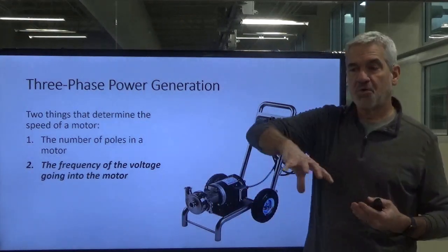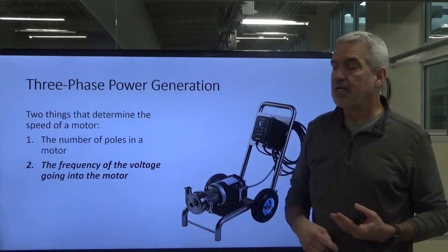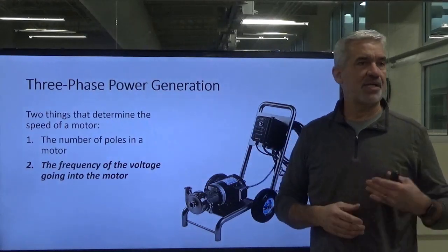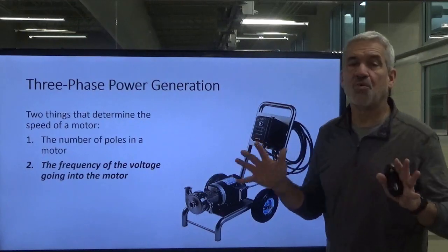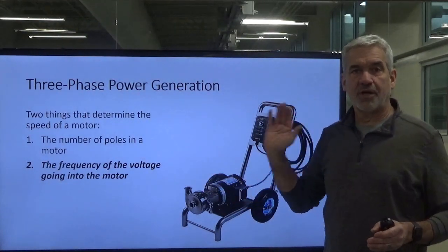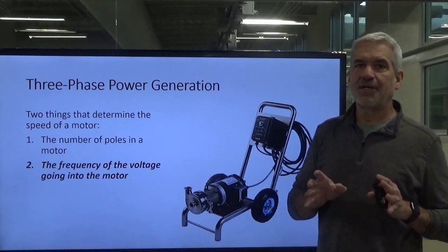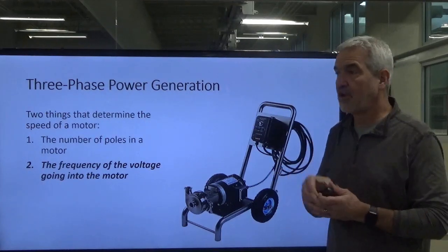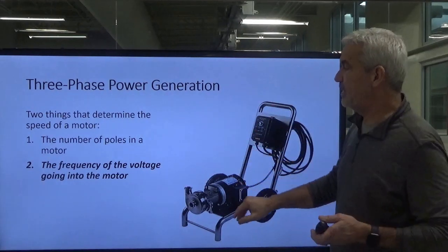That's so they can control the speed at which the rake and plow mix up the mash, keep the mash mixed, and also the rate at which they transfer the flow from, say, mash tun to boil kettle, or boil kettle to fermenter to bright tank, whatever. You don't want to just go full bore with your transfer. You should know by now that this is a very controlled process, and there are various reasons why you don't want to just go full bore with everything. But this is varying the frequency of the motor.